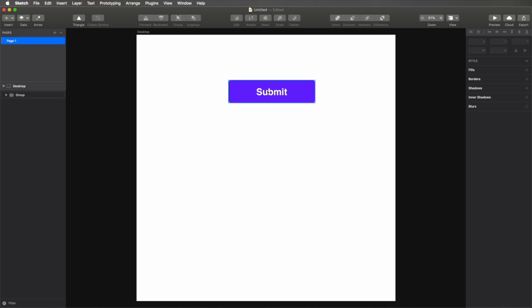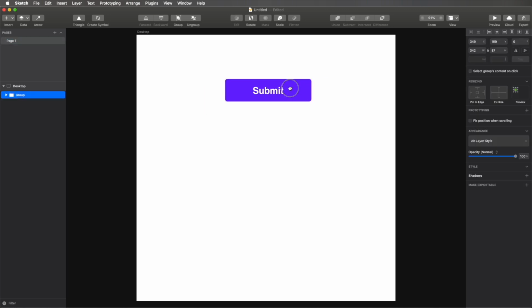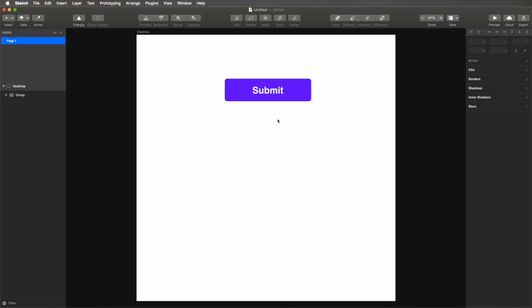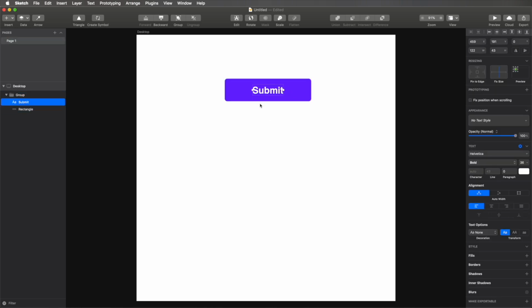But coming back to our problem, how do we keep this in the middle and not resize it? How do we keep the text the same size and in the middle? Well, we have to go here where it says fixed size. For now, this line in blue tells us that the fixed size is set vertically, so its height is fixed.